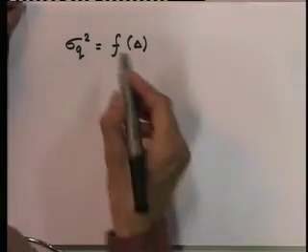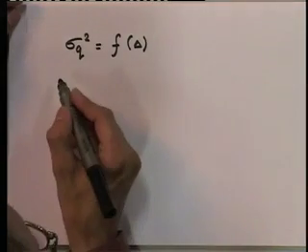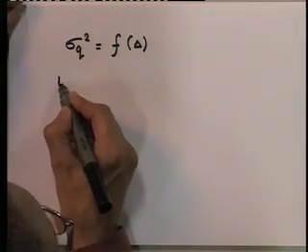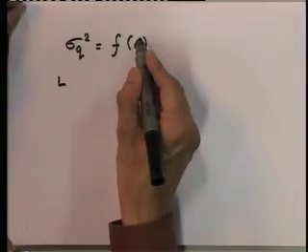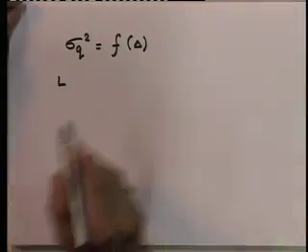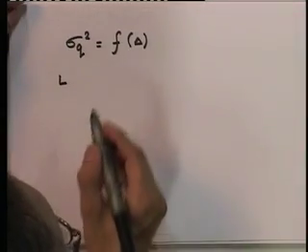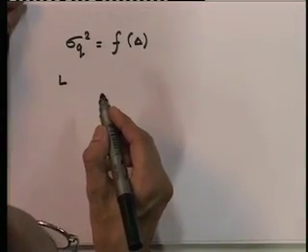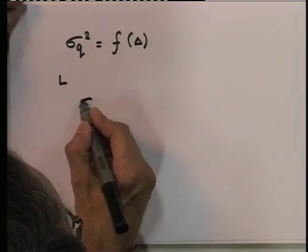Now, an expression for the minimum squared quantization error for an L level uniform quantizer as a function of delta can be found by replacing the boundary and the reconstruction levels in the following equation.